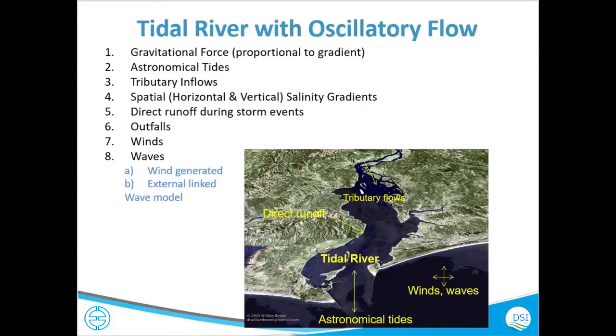If you are concerned right at the mouth, you cannot have the boundary right at the mouth, because all of your results will be constrained or impacted by the boundary. So it's always a wise thing to go a few miles and probably make a circular kind of boundary at the coast, so that all the water can flow in and out without any problems.